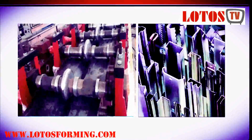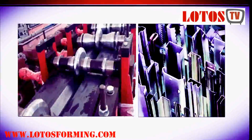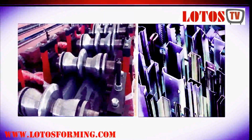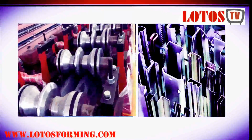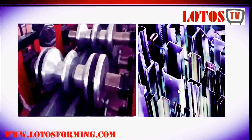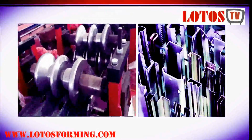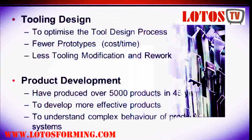And what you can see on the right hand side of the screen are a variety of cold roll form products that we've developed and designed over the years. Cold roll forming produces products with a consistent cross section in a constant gauge. It can be used to process materials from really 0.4, 0.5 millimeters in thickness up to about 8 millimeters in thickness. And we cold roll form a variety of materials, steels, copper, stainless steel, pretty much any formable material, but the majority would be steel or stainless steel.